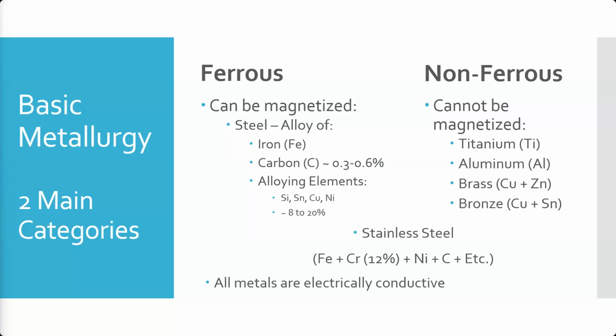So it's a balance between what's the most current I can run before I cause damage to my part by overheating it. That damage can be melting it, to the extreme end, or even just heating up certain parts. Remember, we use heat for heat treatment, right? If you heat a part, it could change the properties of the part. So we have to keep that in mind when we're deciding. So stainless steel, we can run a ton of current through it, but if it gets so hot that it causes the tempering or the heat treating to change, your part becomes worthless at that point. So usually we can get enough field if it's a heavy duty enough part that it's not a big deal.